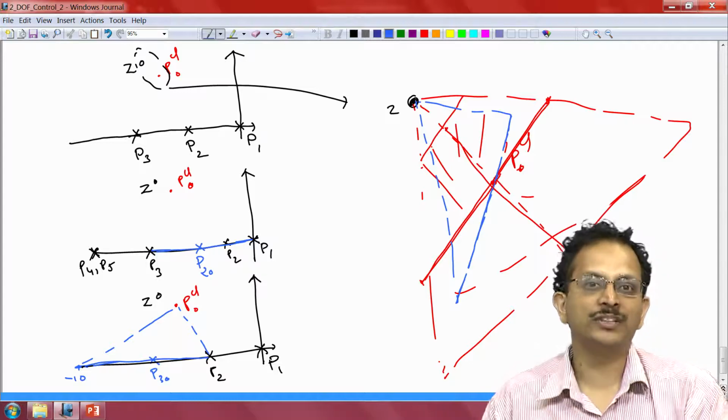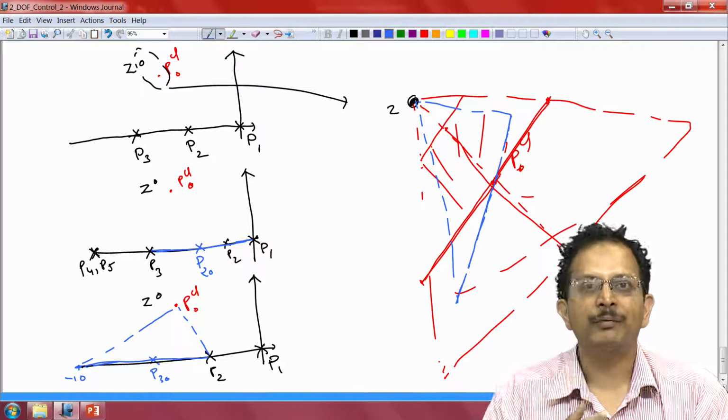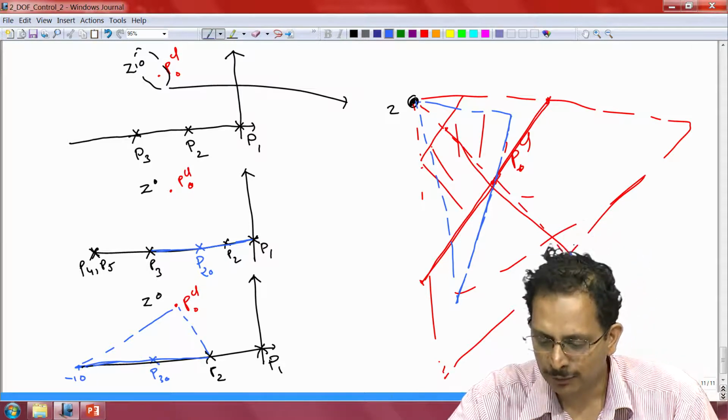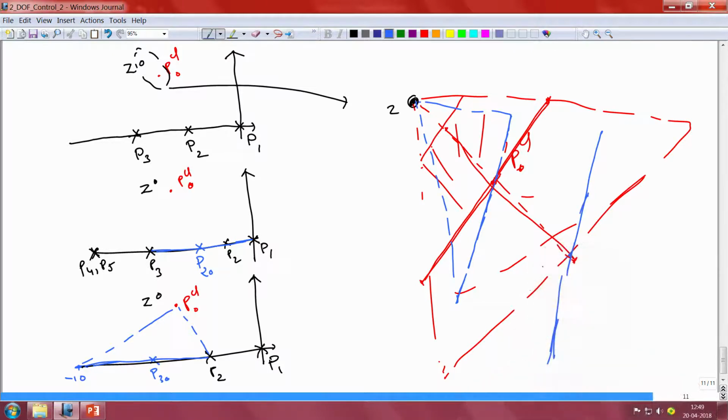However, if once again the pole P3 were to vary between the specified limits, then we would have the closed loop pole varying along this particular straight line in such a manner that it describes another triangle which is similar to the triangle described by the extremities of the point P3 with respect to the point PCL naught.